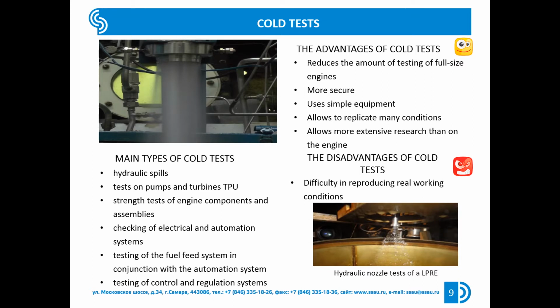cold tests. Conducting cold tests allows to reduce the amount of testing of full-size engines, which significantly reduces the cost and time of testing new LPRE, makes the process of development and quality control of engine components more secure, allows in many cases the replacement of the unique test equipment with simpler and more reliable ones, allows the change of operating modes of components within a wider range than possible on the engine.